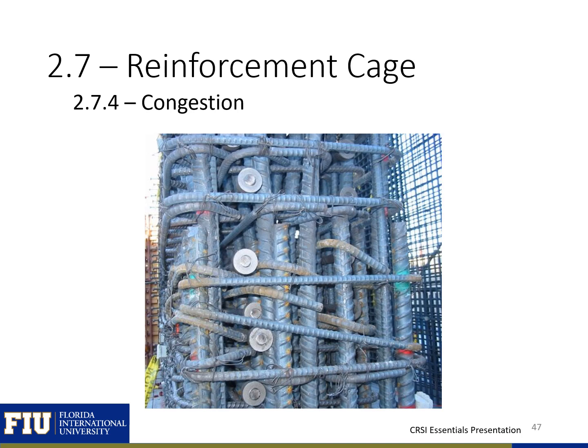Congestion can occur at various locations within a reinforced concrete structure, depending on the reinforcing bar size and spacing that is chosen. It is important to draw details to scale to ensure that all the reinforcing bars fit adequately within the structure while satisfying the pertinent ACI 318 requirements. The photo on this slide shows the congestion in a reinforced concrete column. Headed bars were used in hopes of alleviating some of the congestion, but we still have a lot of congestion in the column.